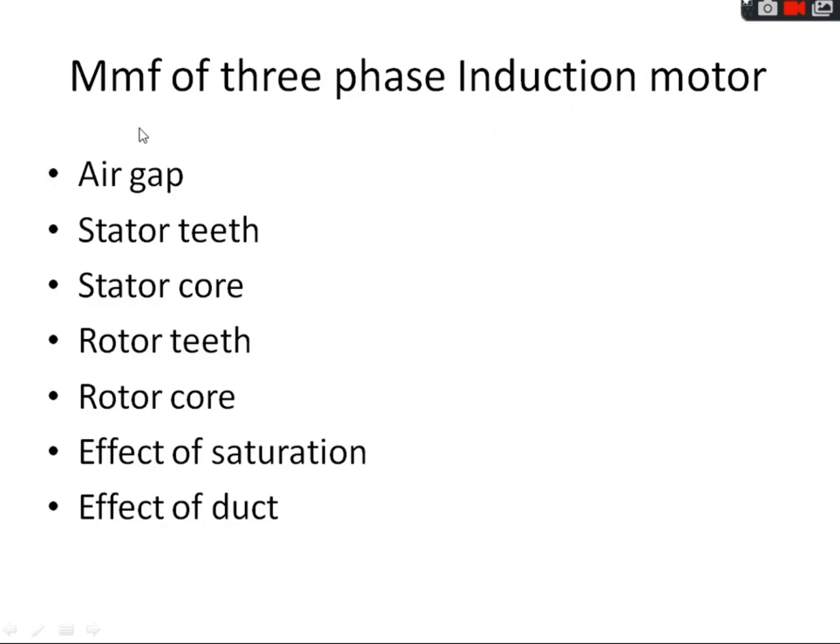the air gap reluctance, stator teeth reluctance, stator core reluctance, rotor teeth reluctance, rotor core, and this mmf is also affected by saturation and if there is a radial ventilating duct present in the induction motor. So let's understand how this magnetomotive force can be calculated, and from there we can calculate the magnetizing component of no load current of three-phase induction motor.